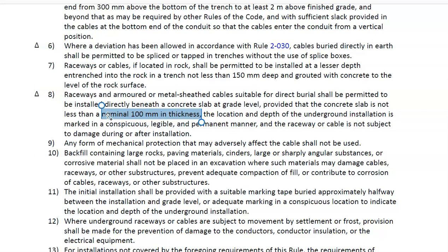Let's talk about clearance and spacings. Clearance and spacings are going to obviously need to be kept so that we don't have electrical shocks. Now, there's going to be clearances and spacings between buildings, as well as between conductors. And then our Canadian Electrical Code is also going to make sure that we're pulled off of anything that produces heat. That's going to be heaters or luminaires themselves as well. If you go into that spacing section inside of your module over there, they talk about air spacing between non-metallic, that's luminaires, and heat sources, ducts, chimneys, things like that.